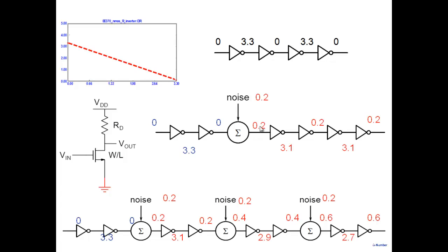Why? Because you introduce a perturbation here. Think of it like a small signal. You applied a small signal voltage, which is 0.2, and you're saying there's no small signal output. That it still stays at 3.3. What does it mean? That the gain is 0. Or if you can't get a gain of 0, so somewhere here, let's say when I'm applying V in of 0, somewhere here I want a gain of 0. Why? Because it will help us in rejecting.